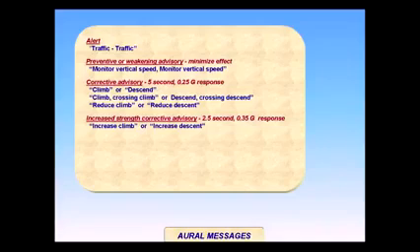"Increase climb, increase climb," or "increase descent, increase descent." Increase the vertical rate to that shown on the VSI. Maneuver at 2,500 to 3,000 feet per minute within 2.5 seconds.